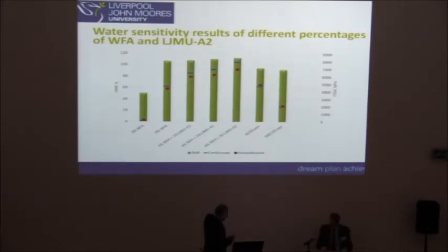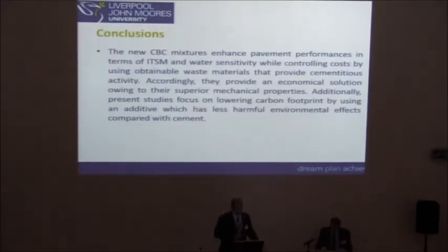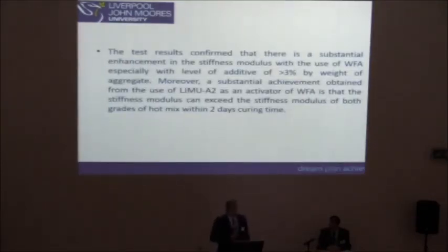and the cold mix. Conclusion: the new cold binder course enhanced the pavement performance in terms of stiffness and water sensitivity, and we now have an economical solution, and there will be a reduction in CO2 emission. When we apply more than 3% of the waste fly ash, we got stiffness modulus more than the two types of hot mix.